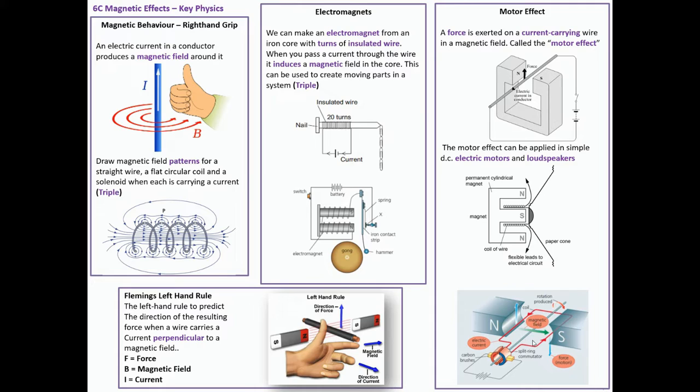We can also, of course, have motors. So electric motor here, we've got carbon brushes, a split ring commutator. So there's a split, which means that as it spins, as we get a push, it doesn't tangle up the wires, and these little carbon brushes will wear away over time and can be replaced. In a car, you would see some of these old-fashioned devices. And the clever bit with this is, although the field is that way, because the coil of wire, the current flows up one way and down the other, due to Fleming's left-hand rule, the force reverses. So force up, current towards us, current away from us, and force down. So there you go. That is electromagnetic effects.